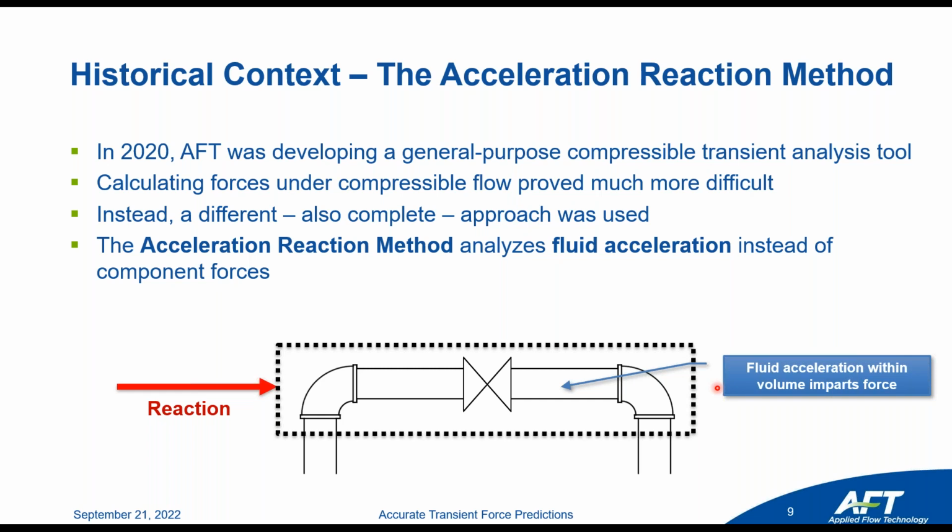One is, I would say, more suitable for liquids, which is the component reaction method. It's not as suitable for gases. The acceleration reaction method works for both liquids and gases quite well. It always is going to work. It's just easier to determine this. So I'm going to let Scott dive into the details on this.